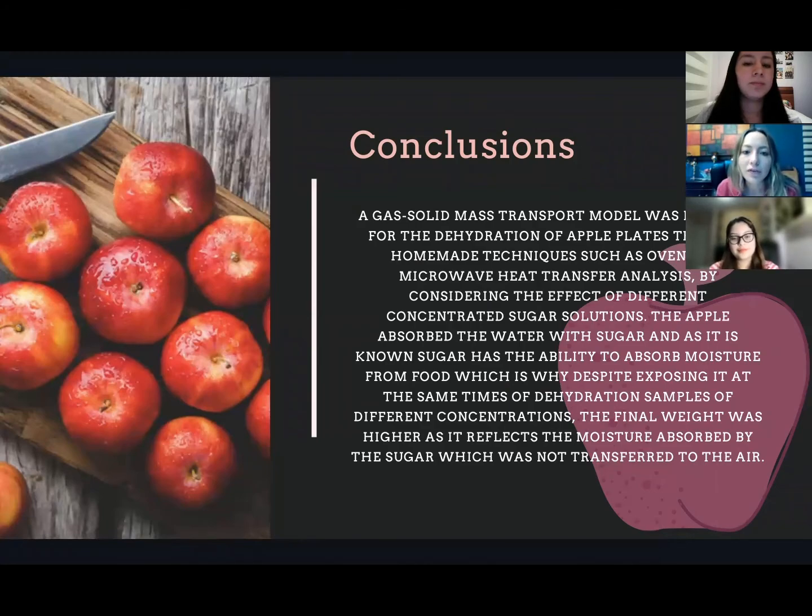Also, for the development of the model, mathematical methods were applied, such as series resolution, and based on literature, mass transfer theory provided an expression to calculate the diffusion coefficient of water lost from apples to the environment of air. Especially, this expression was obtained by making logarithmic graphs of the humidity difference of apples with the environment and applying Excel. The slope was obtained, which means the diffusion coefficient can be determined.